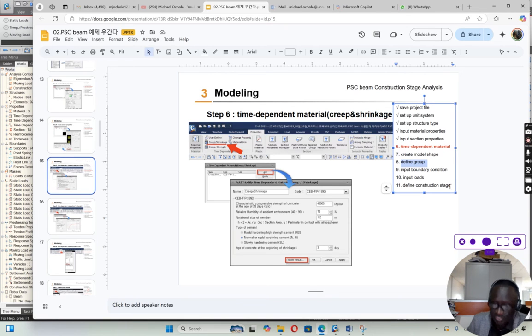So one day now we were trying to discuss with my senior. He had done design close to 6 months. So he was trying to take me through to understand what he has done. So when I was trying to look at, then he discovered that actually when we were checking the different loading, the screeding, services, and live loads, then we discovered he did not activate the parameter for factor for the aspect for self-weight.